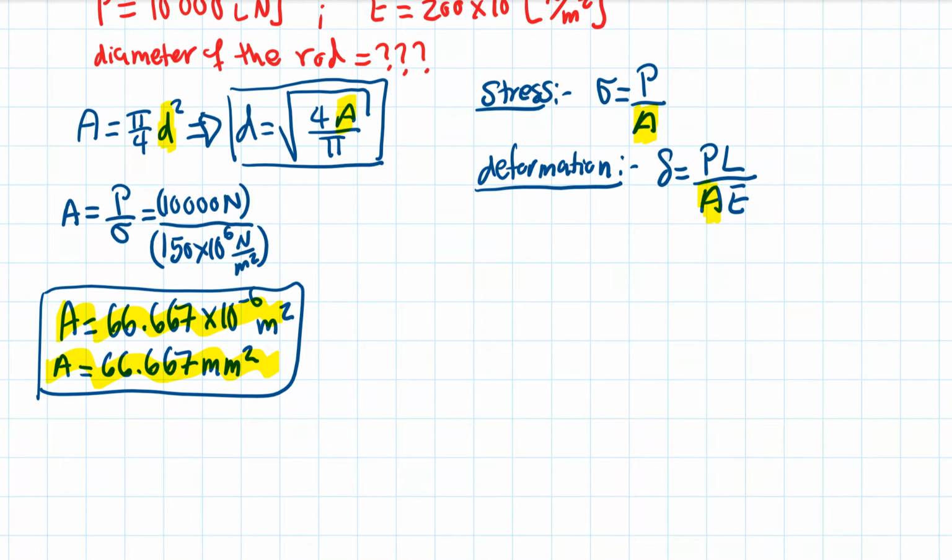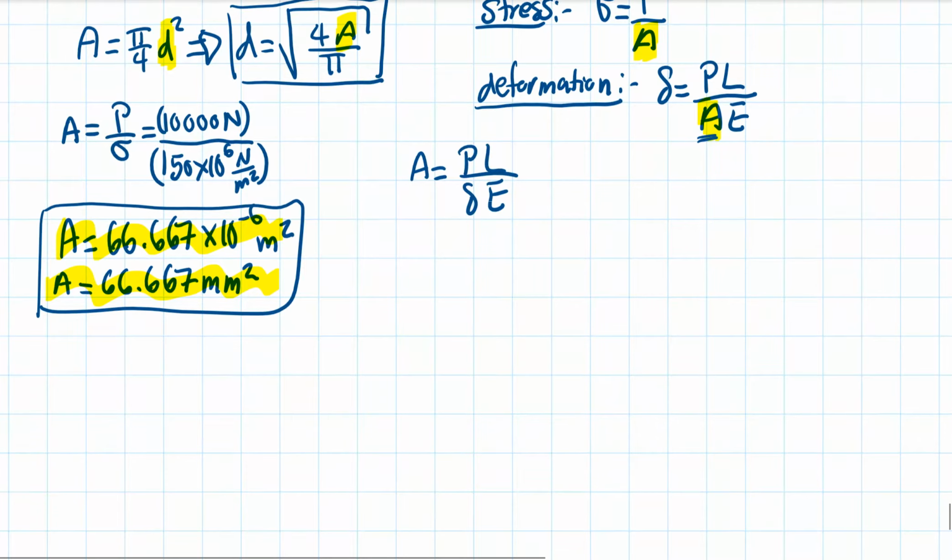Now let's use the deformation equation and solve for area. So area will equal PL over deformation times E. So the applied load is 10,000 Newton.